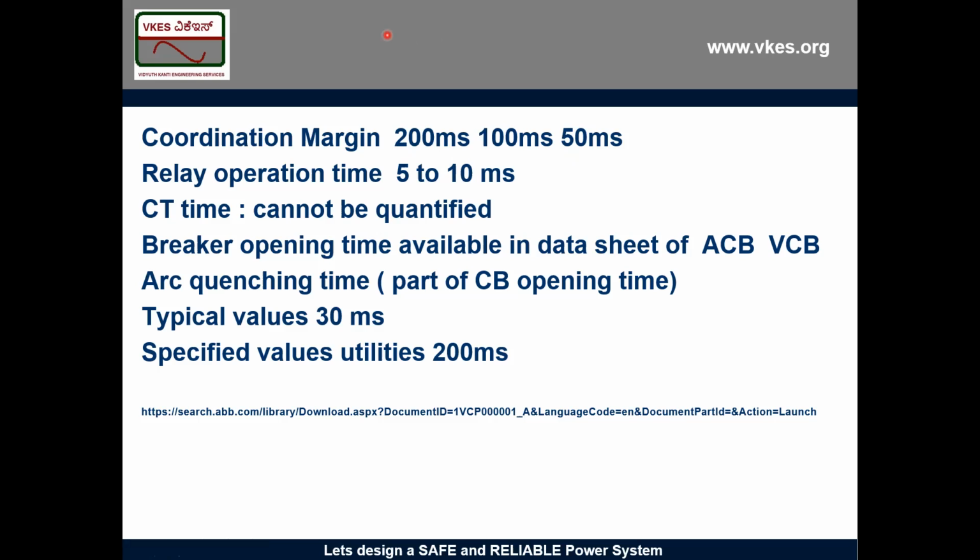Naveen Kumar, sir. You have been doing a lot of relay settings also. What are the coordination margins you came across? It generally depends upon the panel, how many panels are in between the load. Generally 60 milliseconds. Okay.